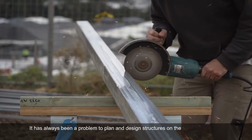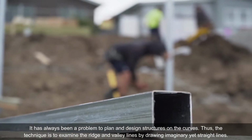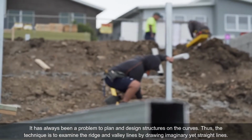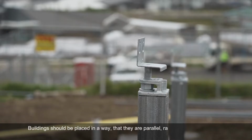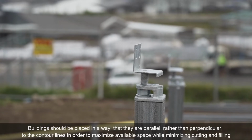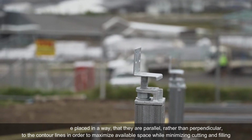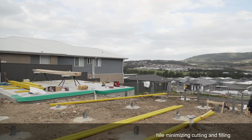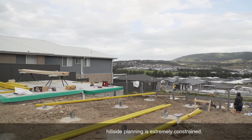It has always been a problem to plan and design structures on the curves. Thus, the technique is to examine the ridge and valley lines by drawing imaginary yet straight lines. Buildings should be placed in a way that they are parallel, rather than perpendicular, to the contour lines in order to maximize available space while minimizing cutting and filling. Compared to the plains, hillside planning is extremely constrained.